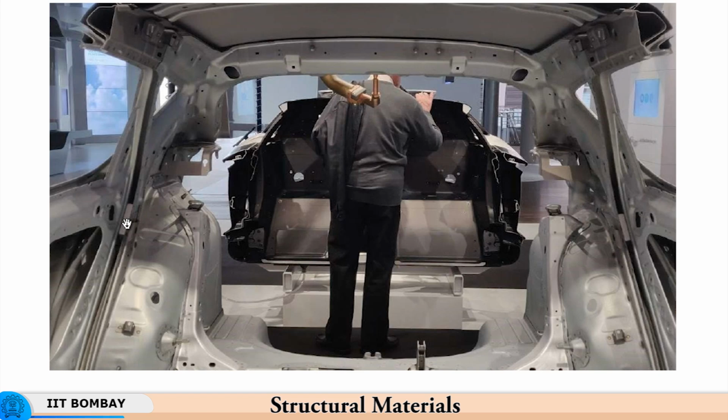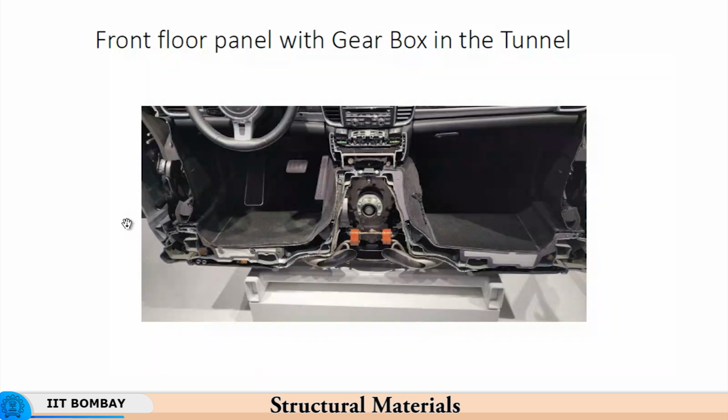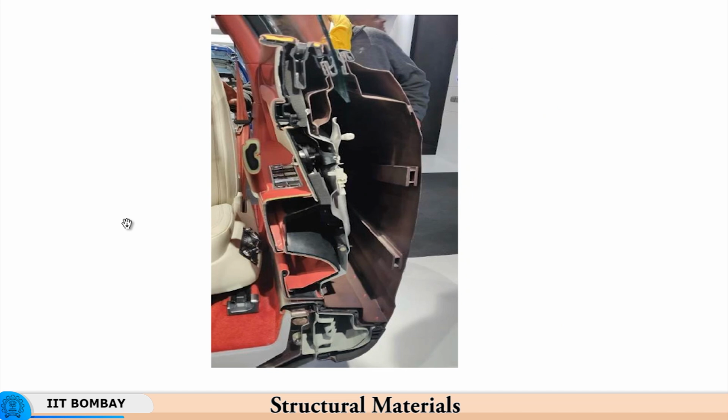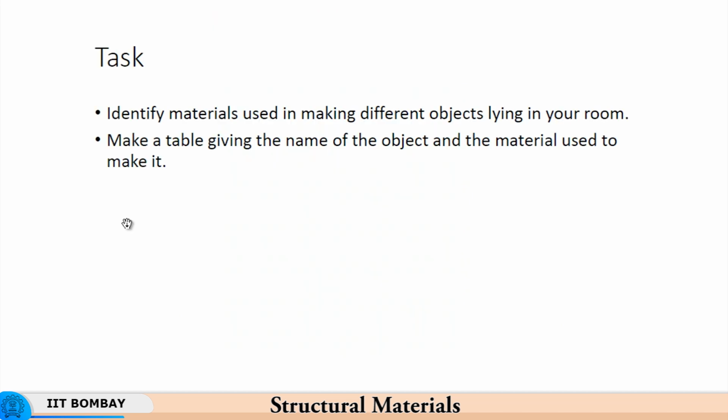Different criteria have to be satisfied by each of these materials, and therefore even if you are using metal, it is not that the same chemical composition of metal is used everywhere. Be it the floor or the car body, the chemical compositions are going to be different. So different grades of material are developed, and materials are heat treated to different strength levels.